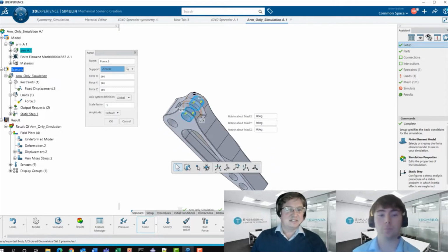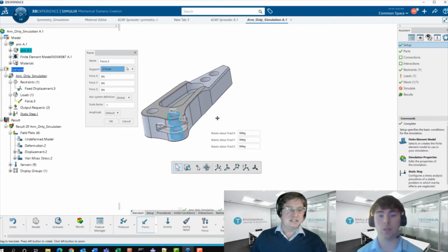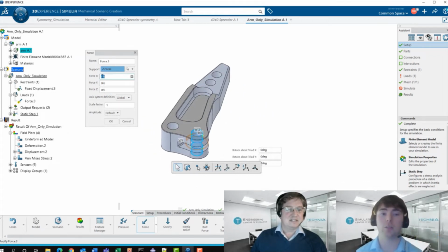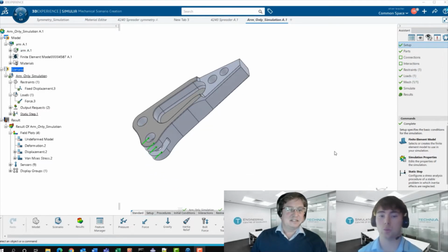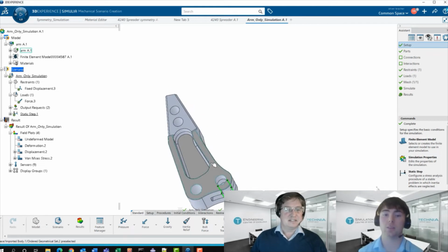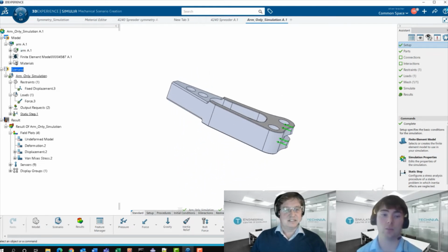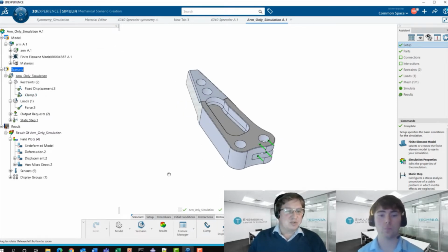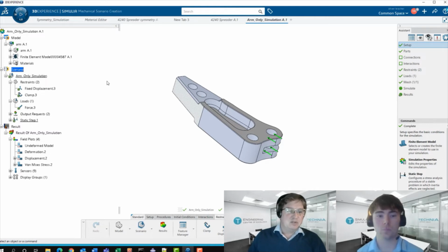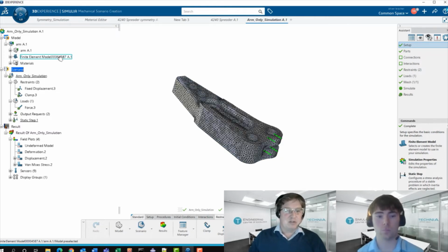We can then apply a force or a displacement with a connector to represent the short link, which is transferring the load from the piston to the arm. Or we could use a coupling or constraint like the other pin, but apply loads to that. All of these methods will reduce the complexity and the computational demand. Oh, okay, yeah, that makes sense. We know the maximum force the hydraulics produce from the manufacturer, so we could use those as the boundary conditions.